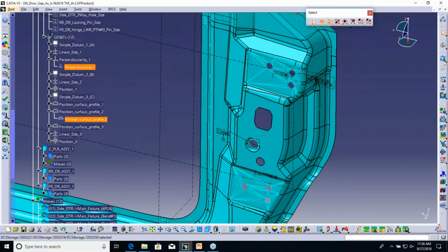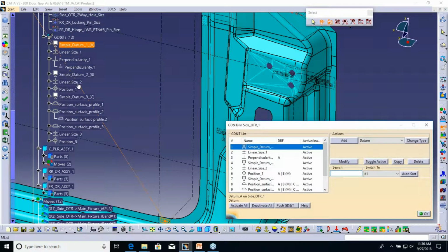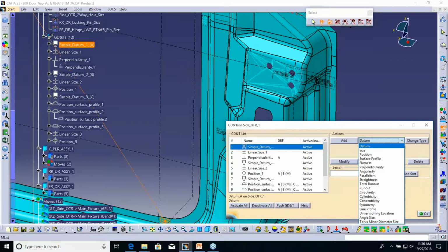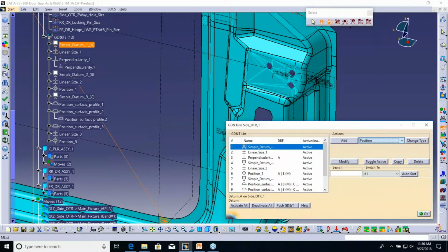Otherwise, you can also say I don't even have FT&A or have the capability of using FT&A. You can define the tolerances or GD&T within 3DCS. So if you have a fixture that has any tolerances, you can use this new functionality to define whether they're datum targets, datum points, whether you would want to add size or position, any of these, and they would be defined as GD&T within 3DCS, and it's used within the analysis.